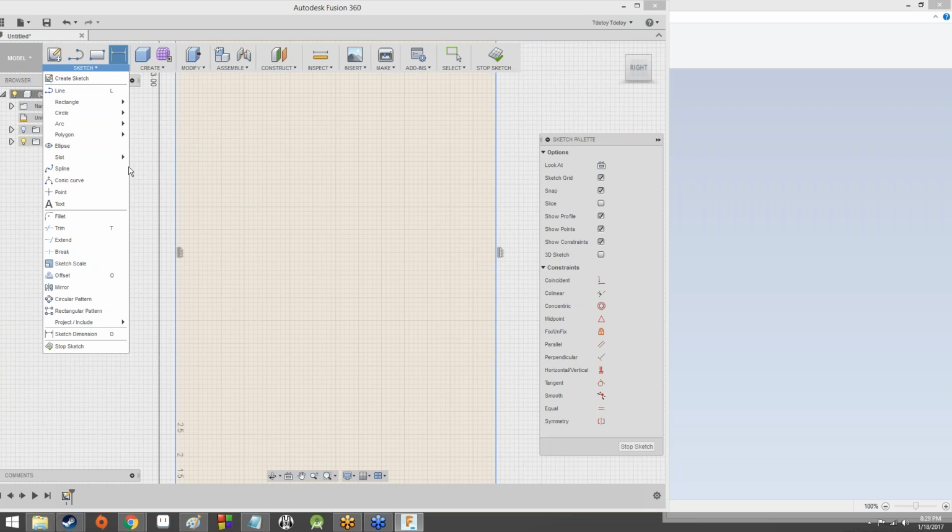Oh, you went down to Sketch and then clicked on Sketch Dimension? Yeah, you want to click on Sketch Dimension in order to be able to do that. Sorry, did I skip that step? But yeah, you definitely want to have Sketch Dimension selected in order to be able to do the dimensioning thing. Does that help at all, Cohen?